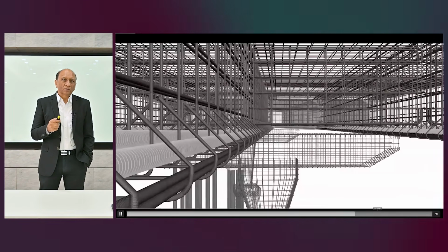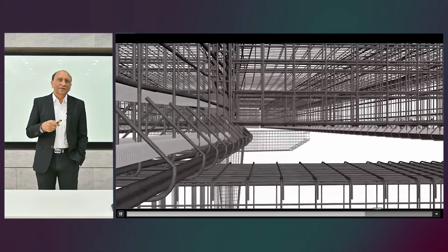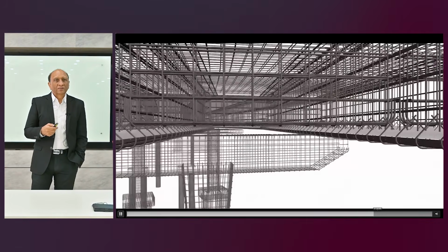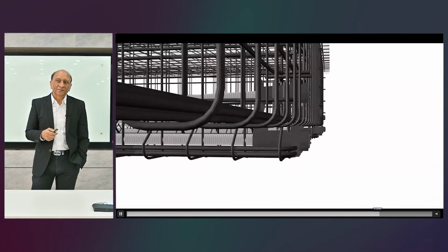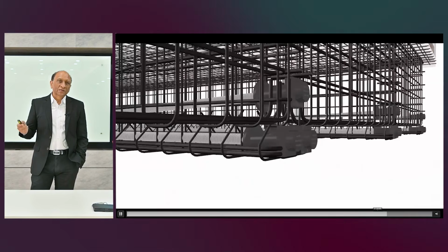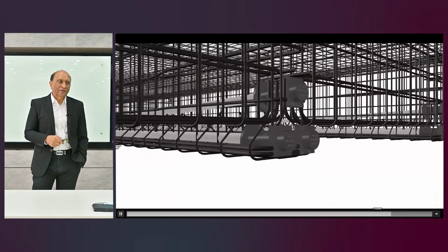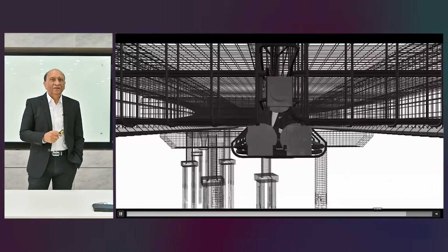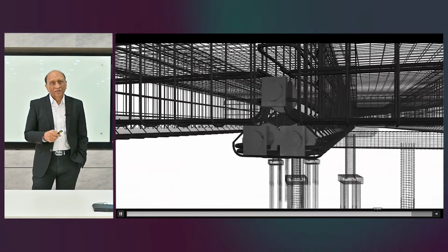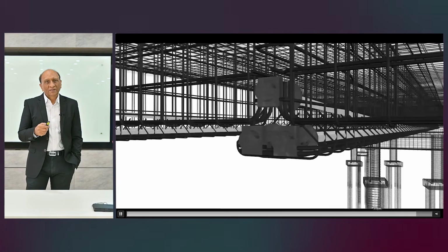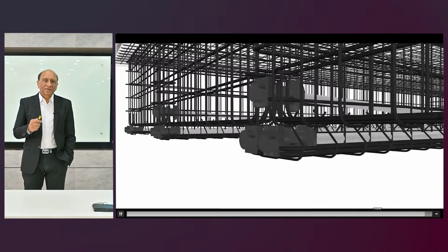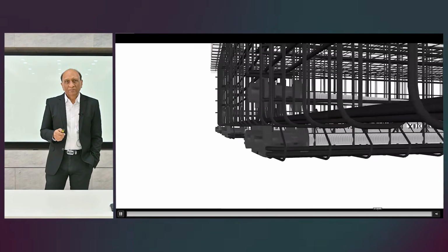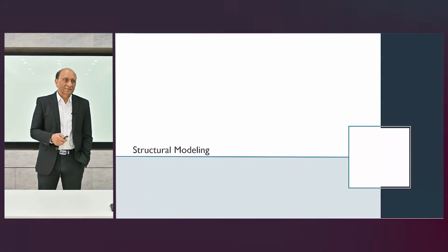Because it's all there, it can be used later for, for example, nonlinear analysis. If you want to do pushover analysis, the reinforcement is already there, so hinges can be extracted from them automatically. The tendons are already there, and the tendon forces can be applied to the bridge automatically. Having all this information completely defined saves a considerable amount of time, but more importantly, consistency.